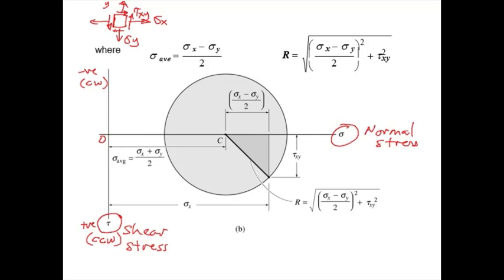So there are two approaches to actually draw the Mohr circle, depending on which textbook you follow. Now, this diagram here is based on Hibbeler. What it says is we use the centroid of the circle. We find the centroid and you find the initial point. That is normally called point A, which is the stress condition on the x-axis. So we have the x-axis there.